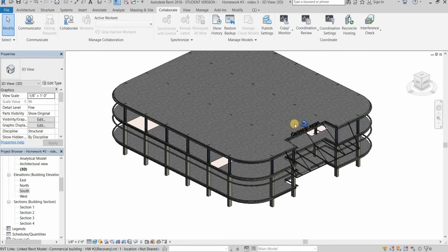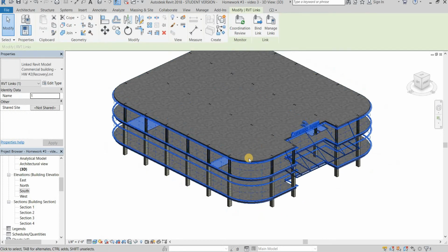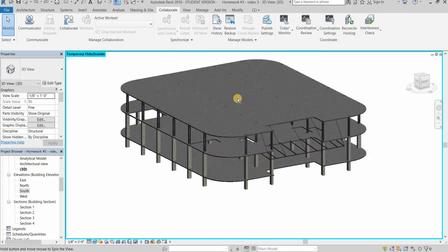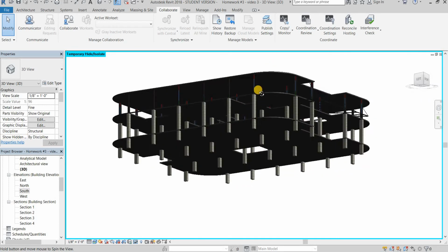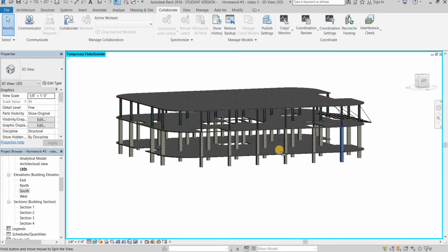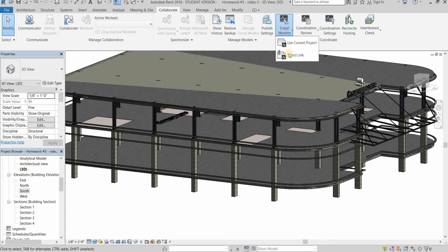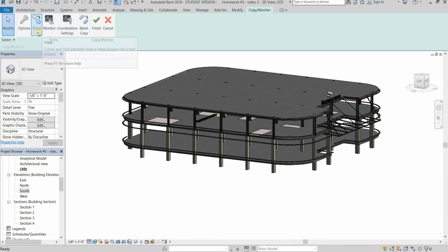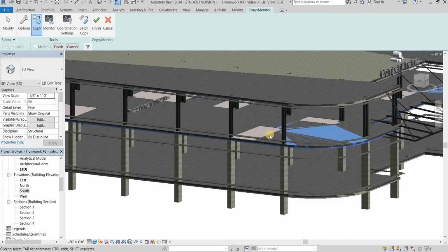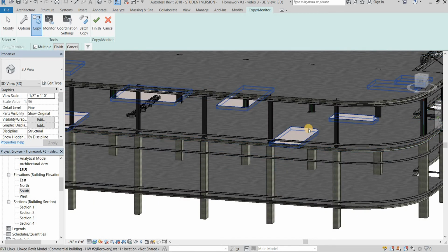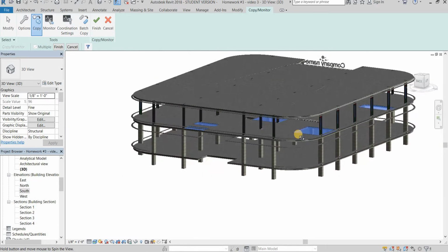Now, when I go to my Revit link and temporarily hide it, I just have one slab. So I have these slabs here, and in my case, I have some holes here. So I'll try to fix this by doing basically the same thing again. I'll just Copy Multiple and click here. Where else? Not here. Here. Yeah, and I should be good now.